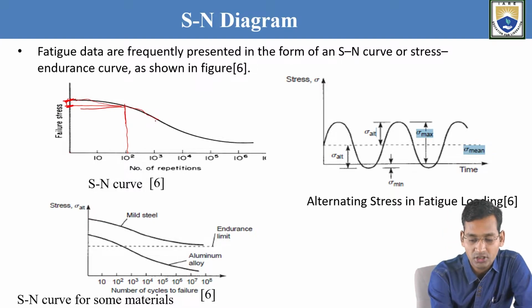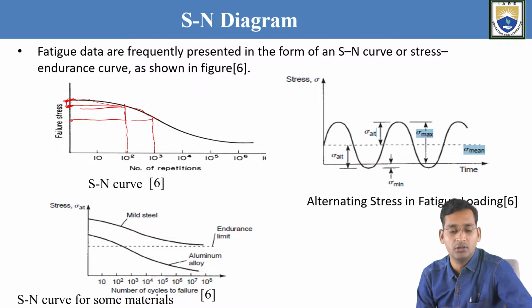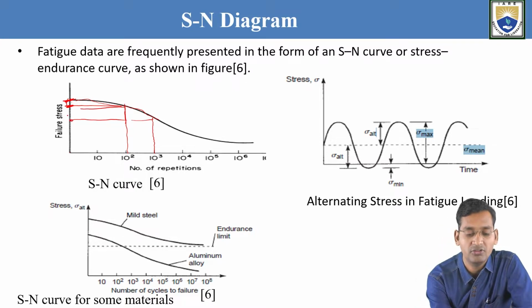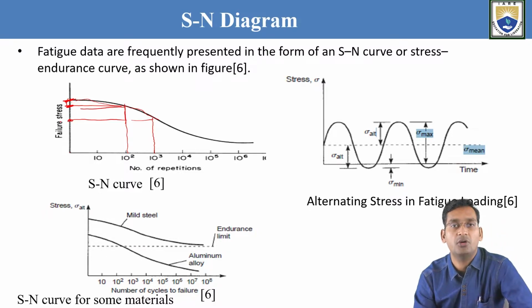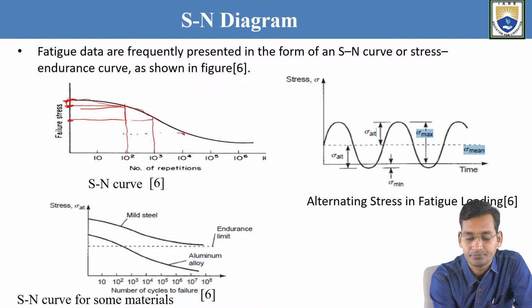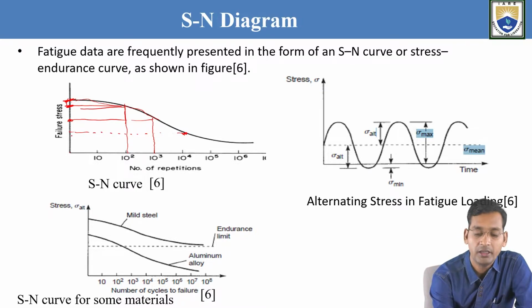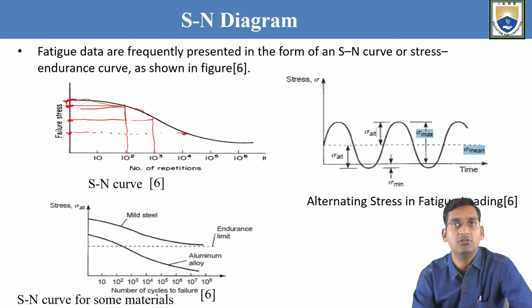So now come to 1000 cycles, right? So at 1000 cycles, now just see here. At this stress only, once you have used it 1000 times, once the stress level reaches this level, that material or that body will get cracked. Come further to 10,000 cycles. Now just see here. This one. So after using it 10,000 times, at this only it will fail.